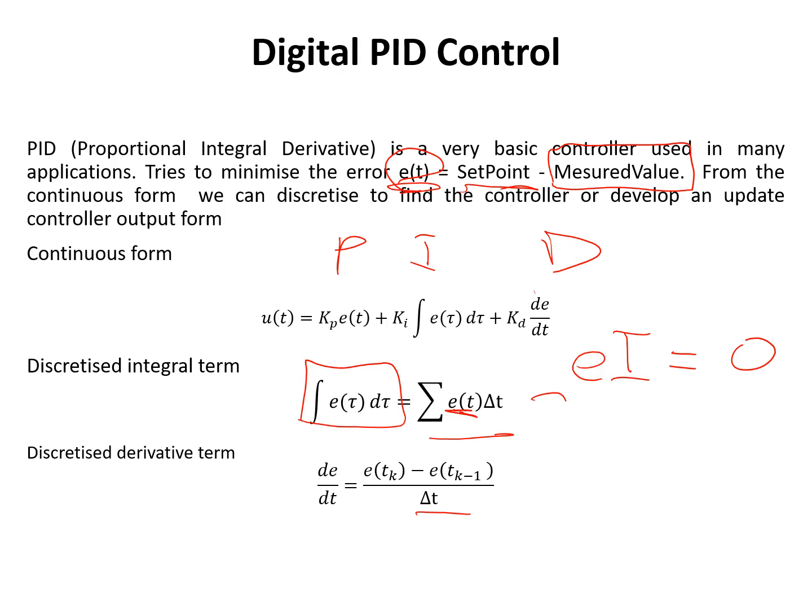Again, really the controller should be running at a frequency that is at least typically 10 times the bandwidth of the system you're controlling. So if the dynamics of your system is 1 Hertz, then you need to at least run your controller at 10 Hertz. That's the minimum, generally, rule of thumb that you can use.